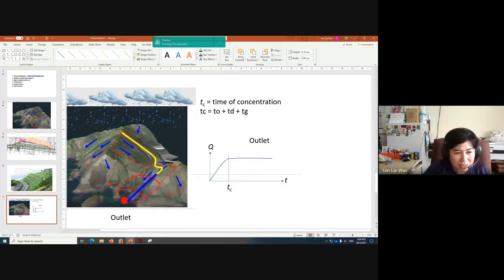Now, how are you going to determine the slope? Of course, you have invert level, right? Sorry, not invert level, you have ground elevation. You need to get the ground elevation at any 2 points, you are just assuming, right? At any 2 points, you can get the gradient of this slope here. Then the length you can determine on the plan view or plan drawings, and then you have to account for the slope as well. You can get the length of the overland flow. Clear?